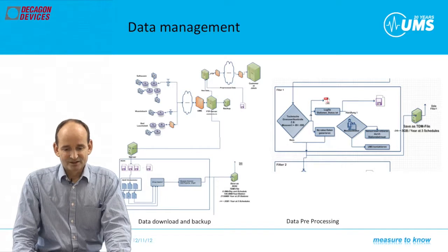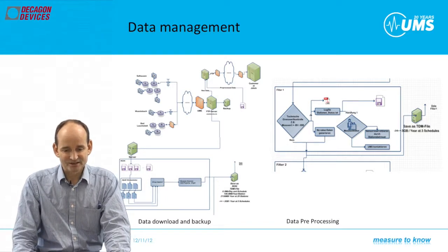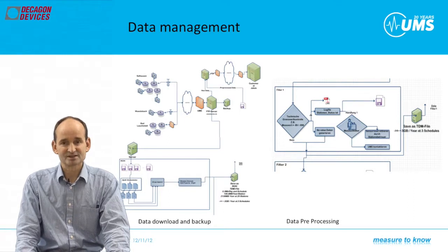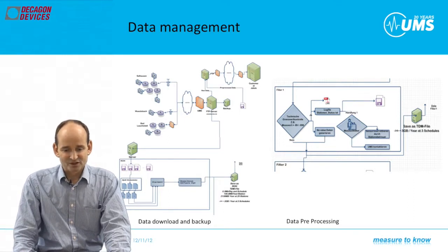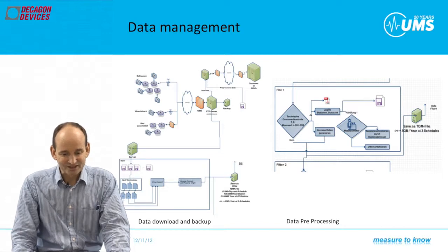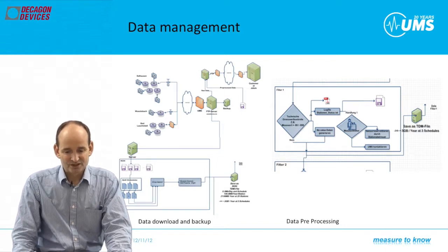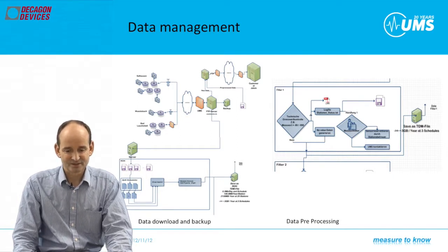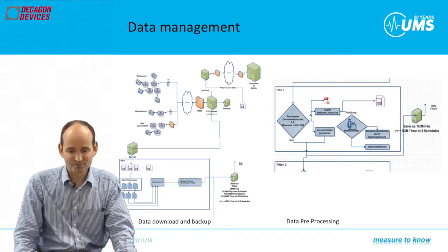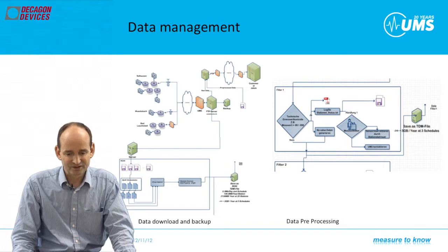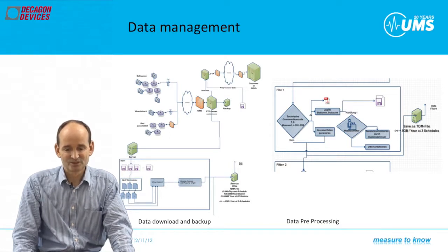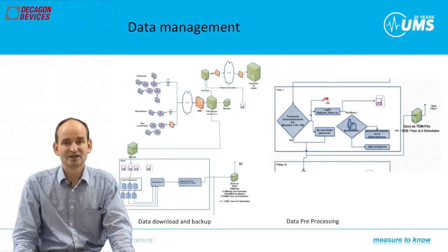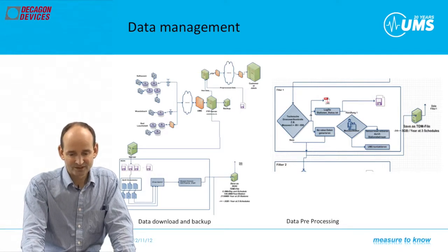Regarding the data flux, you may have different locations and loggers sending different data. So for long-term monitoring tasks, a well-designed database is required. The data may go directly onto a web server, which is in most cases a preferable solution. Anybody who has the access address is able to download and work with those data, but the initial data set keeps untouched. Also, the process of downloading the data from a logger is now standardized, so no mistakes happen anymore during handling in the field by downloading data.